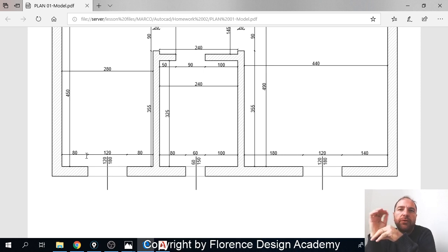and that is that today we will talk about layers in general. One practical use of layers will be changing line weights, but also colors, as we've seen. I'm telling you that lines in the hatch are not black, but grayish, and with layers we can also change colors.